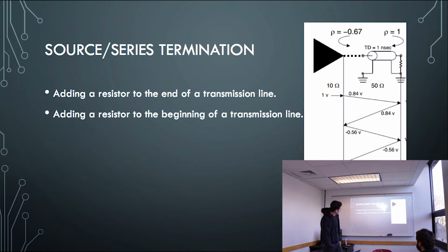Well, there's two types of ways. You can add a resistor to the front or the back. So what you want to do is you want to keep the characteristic impedance the same across the entire line. So say this is your endpoint. You're just trying to communicate over UART, and essentially you just have a point-to-point, but the endpoint into the other IC is like 1,000,000 ohms.